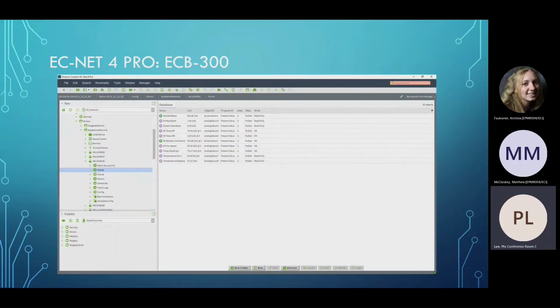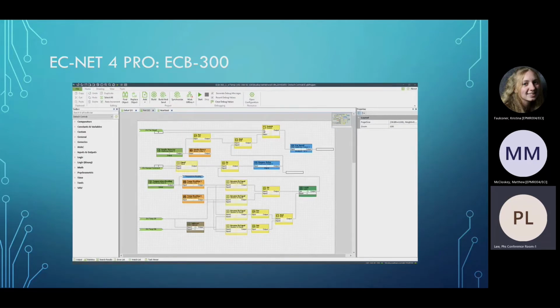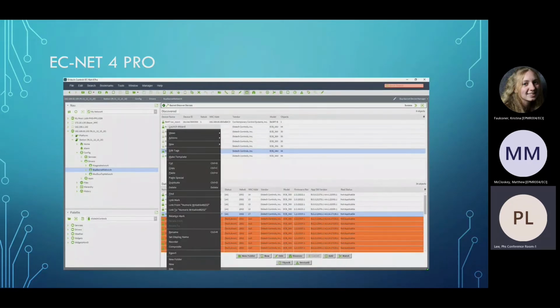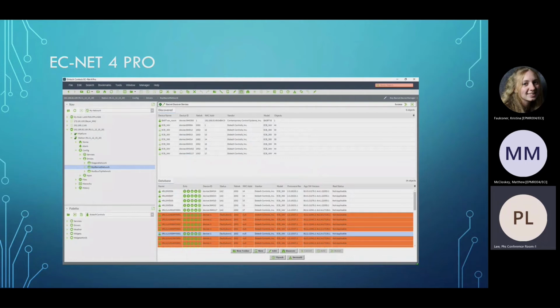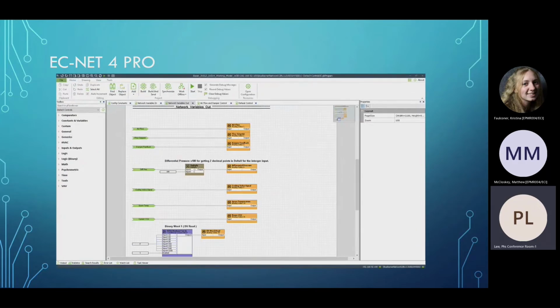Okay. So now we're going to dig down into how to point the bacnet points to the modbus points. It's probably the most critical part of this meeting. So in each device, as you can see, we're in the station. We're in the drivers section. We're in the BCP bacnet driver specifically. In that drop-down menu, there are those devices, which we saw right here. All of these devices will be in that drop-down menu. So we are there now.